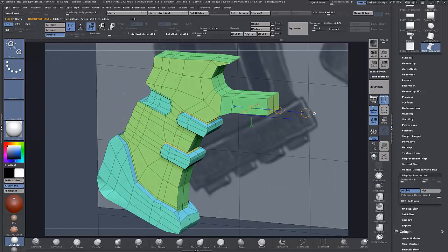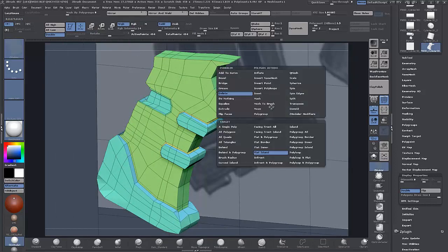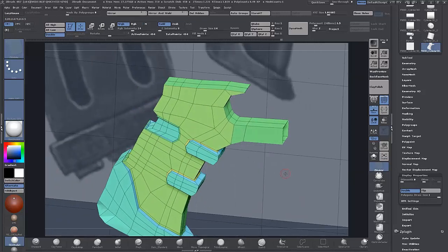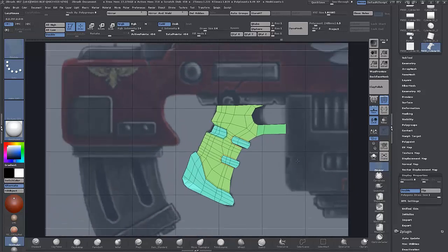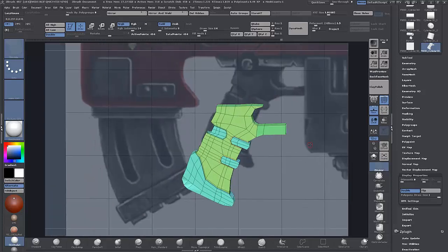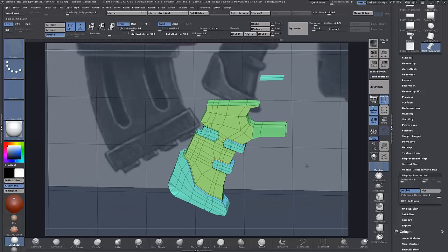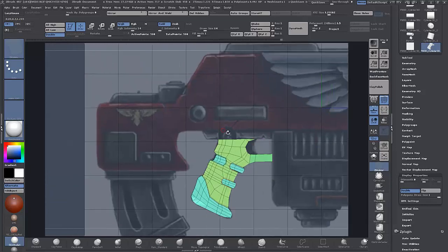So we'll also want to do that, and I'm also going to just delete these here, delete those two, and the ones on the top. I might just take one. I'll tell you, actually, we can take some of these and just bring them up to use for the top. So what I might do here is just go to Q mesh, and we can just steal this by Q meshing up, and then just Q mesh up, and then sorry, I'm pressing shift. You want to press control, and you can just break that off and clone that bit of geometry, and we'll use that for this other piece above here.